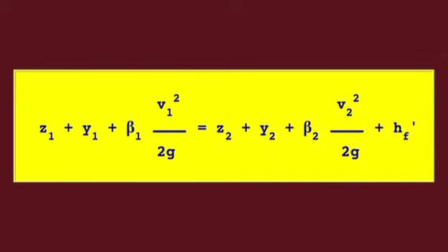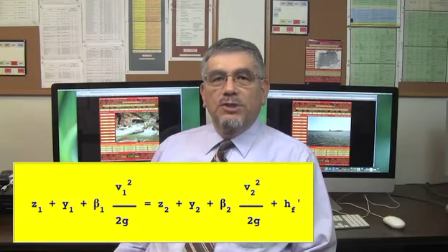The substitution of all external forces into the statement of conservation of momentum leads to this equation, which is similar to the energy equation, but with momentum coefficients and friction loss. The energy equation measures internal losses. The momentum equation measures external losses. The losses have a tendency to be equal.